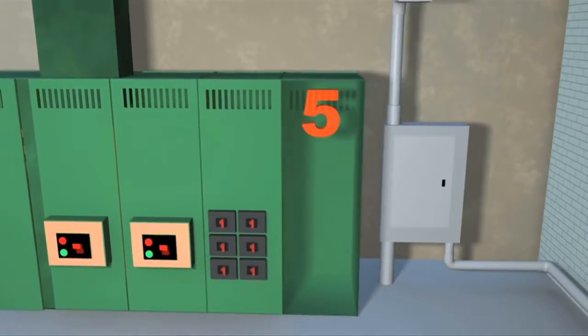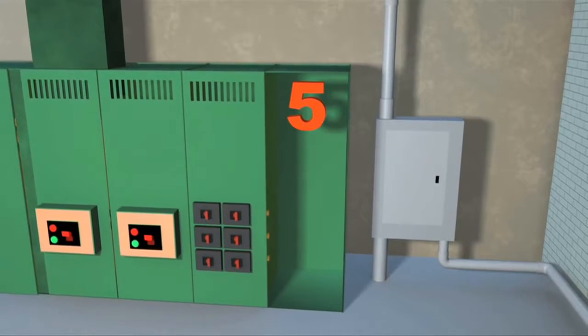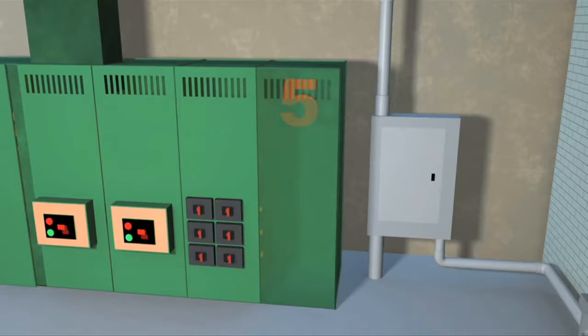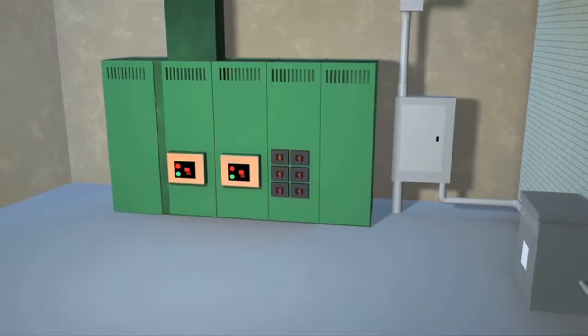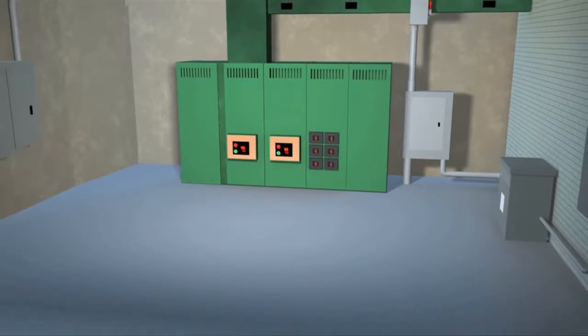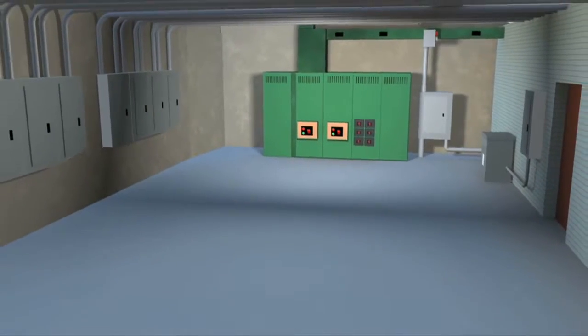The 5th and final section of this switchgear is empty with a solid or blank panel cover. This could be a spare section for future expansion. A blank front does not necessarily imply that the section is a spare. It is important to ask what is the function of this section and is there something in there that needs to be tested.